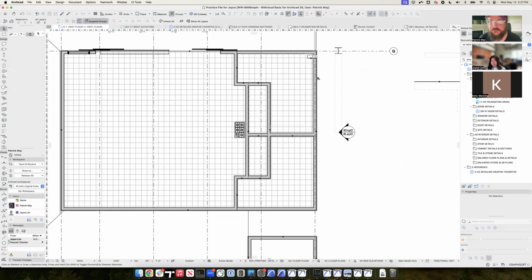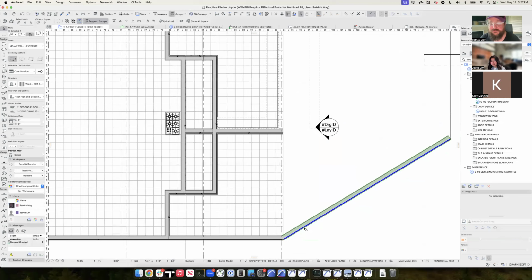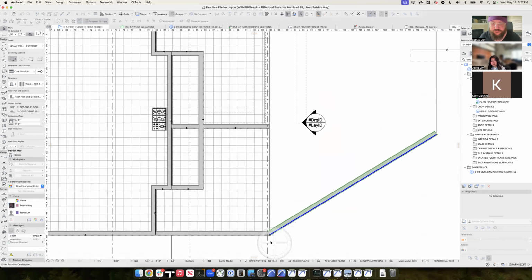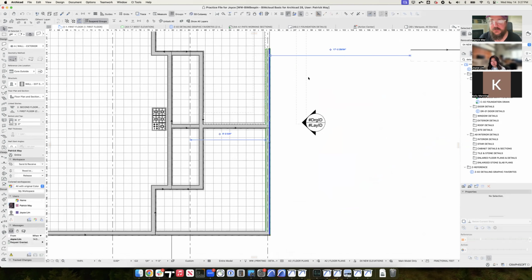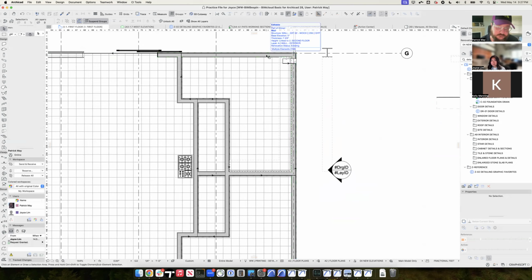Sometimes if it's off by just a little bit, what I'll do is move it way off so it's not almost ortho, and then I'll use the rotate command to rotate it back into ortho. There's little things like that that you can do. Generally speaking, as long as you're holding shift and direct inputting into the tracker, shift and R, you should see that things are basically maintained orthogonally pretty effectively.